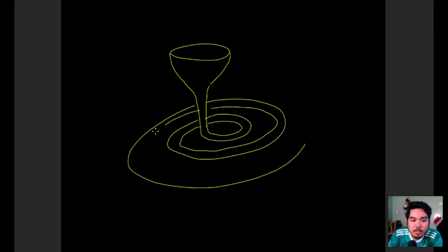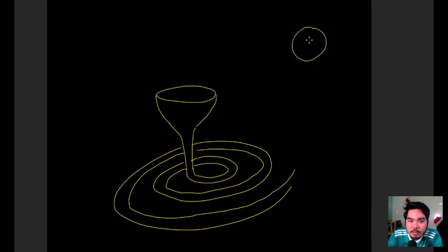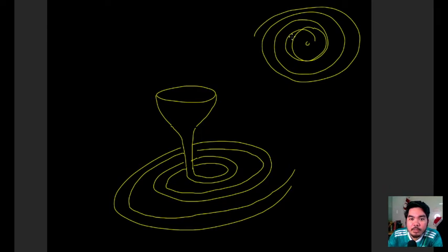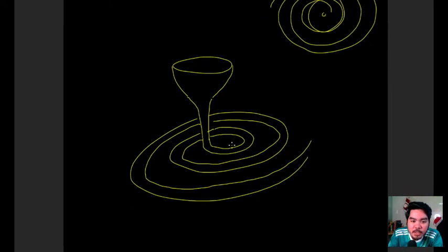And so on and so forth. It can be of some great length, no? And I hope you can imagine this fluidity tester. So this is its top view. This is the pouring cup, and then there's a spiral like that. Again, the way it works is, you measure how far your liquid metal reaches before it solidifies.